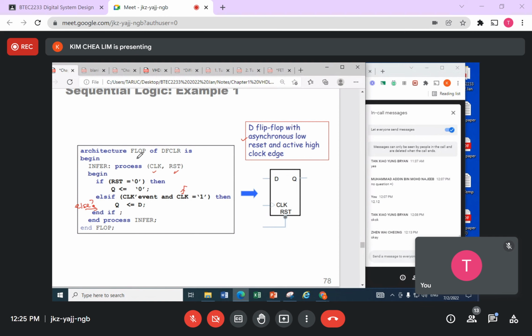So you go and send this program for compilation. No error, no problems. Maybe they give you a warning. Remember the warning? I ask you to forget about the warning. Logically, it's correct. So the system infers a latch for you in this case.